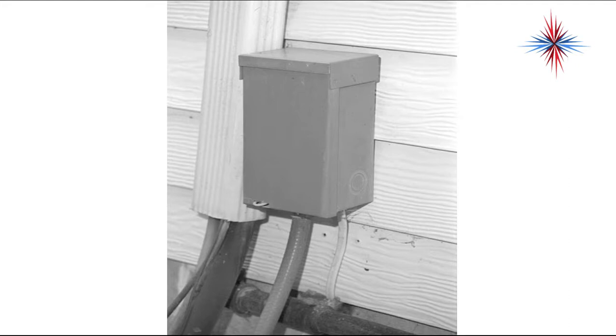It's on the external side of the building, and it is your point of connection for air conditioning condensers into the main system. Usually anything from the disconnect back to the panel you have to have an electrician take care of. From the disconnect to your equipment, you're allowed to deal with. So there is a point of delineation here with respect to your licensing. It's very important to check with your home state or the state you're working in to make sure you know exactly where an electrician is required and where you're allowed to work.